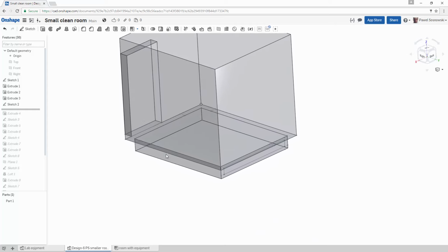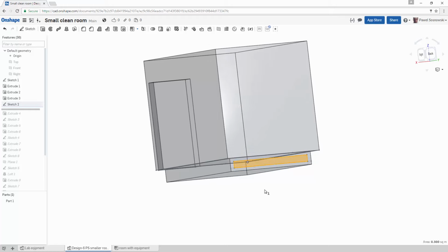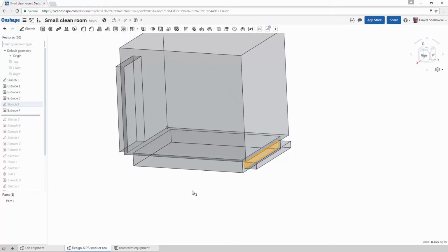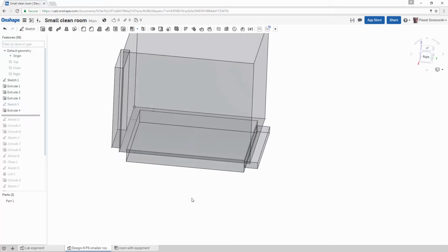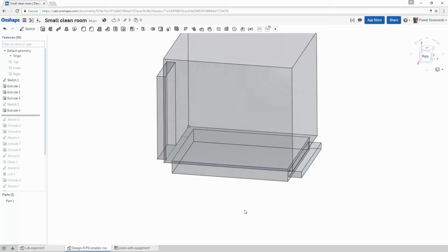This would be enough to have the outlet set if I were to create this particular face that I am marking right now. But obviously, as we already said, it is good to extend the outlet in order to avoid some kind of recirculations that might be happening next to it. And this is exactly what we've done. We extended the outlet just a little bit. It is hard to say. I mean, this is just an example case. It might be advisable to extend it a little further, but for this purpose, we keep it as it is.